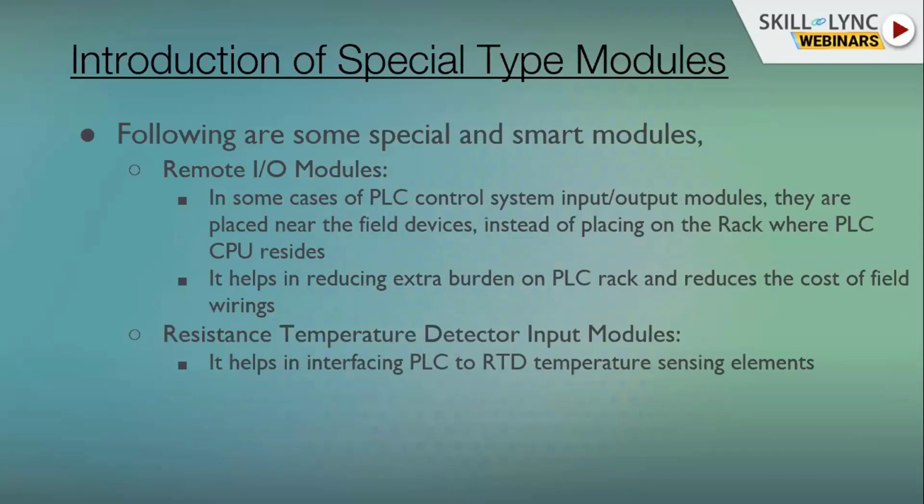Remote I/O modules are used nearer to field devices, unlike modular PLC input modules, which will be housed in a control panel near a control room. Sometimes we'll have an array of machines with similar function. We will have their control panels together in one control room, which will be far from the machines.